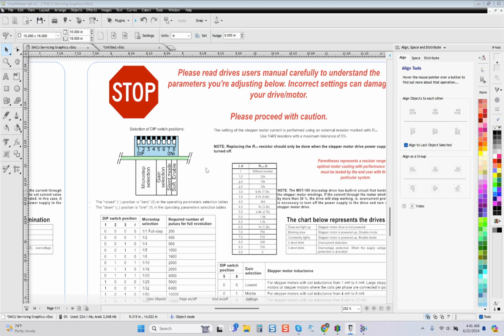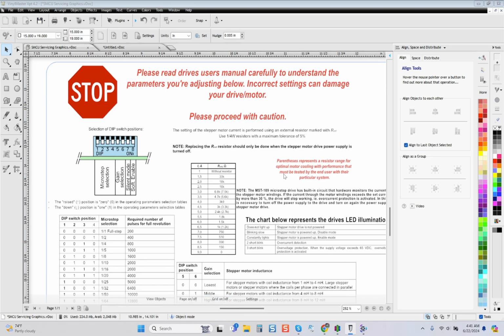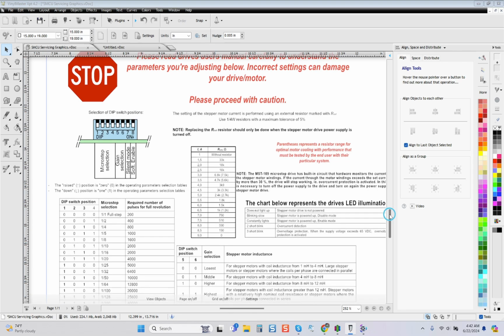Now, another thing you have is, and this is not really discussed here, but just to let you know, your standby on the motors. Naturally the drive will turn itself off within a few seconds of the motors being stationary, and once again they're not moving, so it reduces current to provide holding torque, but once again not draw as much heat.